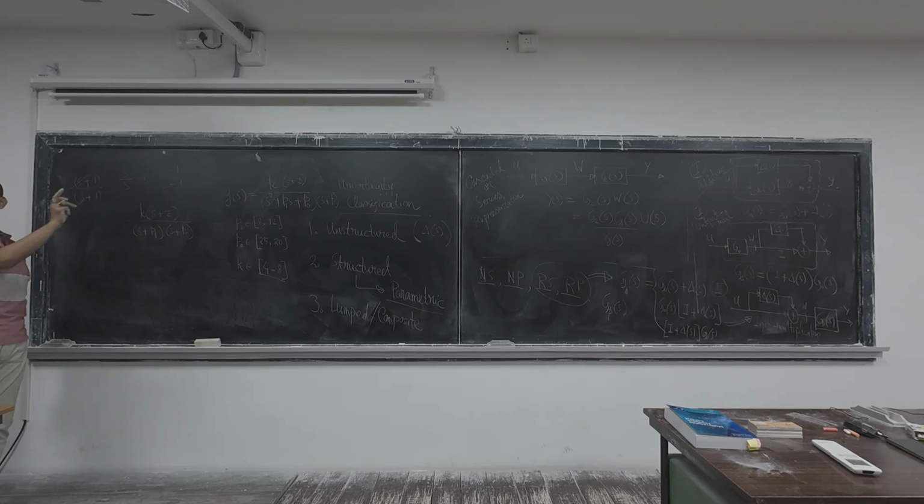When we study internal stability, I will specifically show you why unstable pole zero cancellation causes a lot of headache to us. Please note down that a stable pole zero cancellation, although undesired, doesn't cause a stability problem. Whereas a pole zero cancellation on the j omega axis or on the open right hand side may lead to instability.